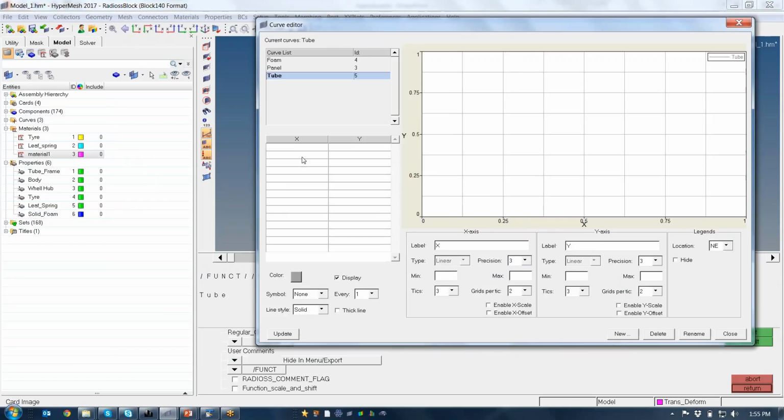This is not the regular full stress-strain curve in this material. It is a curve between true post-yield stress versus true plastic strain. It starts with 0, and your first point will be the yield stress of the material. So I'm just going on with it, trying to create a curve.